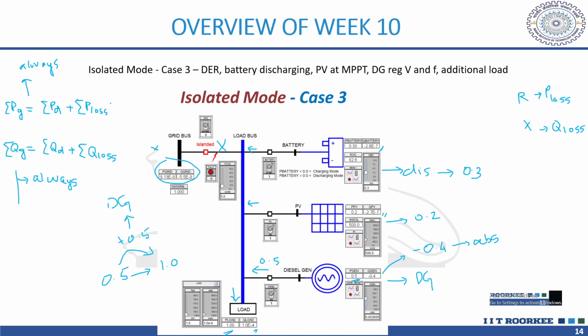But actually, in the case of active power, who is generating and which is the demand is very clear, right? Generators will generate, load will consume the power, and in the delivery process, some energy will be lost. But we can't say that always about Q. Because for Q, except for your generator and load and lines, we have many other sources of Q in our system. So, do you remember about half line charging?